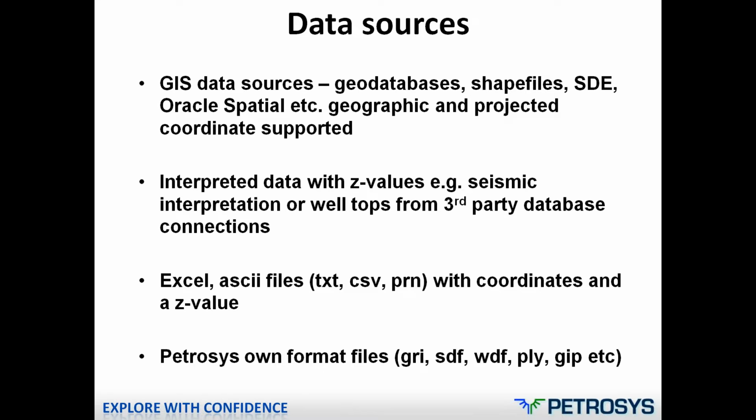There's a wide variety of data sources you can use for input, so things like GIS data sources, geodatabases, Shapefiles, Oracle Spatial. We've got support for both geographic and projected coordinate systems. We can also load interpreted data with z-values, for example if you've got seismic interpretation displayed or well tops from a third-party database connection. And we can load data from Excel or ASCII files, as long as they've got coordinates and a z-value. And of course we can also load data from Petrosys' own format files, things like grids, seismic and well data files, etc.